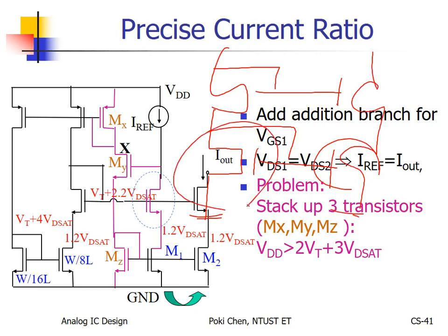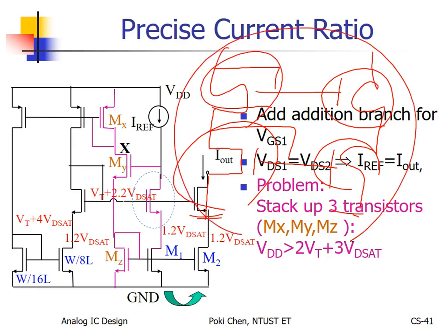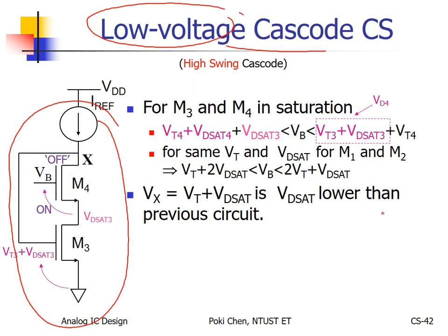My partners. For the cascoding transistor, it also needs bias voltage. Who supports it? Again, its partners. But by such kind of traditional cascoding, I told you already, the voltage here needs to be 1 VT plus 2 delta V, too much. So how to reduce the supply voltage requirement? Low voltage cascode will be the best solution here now.